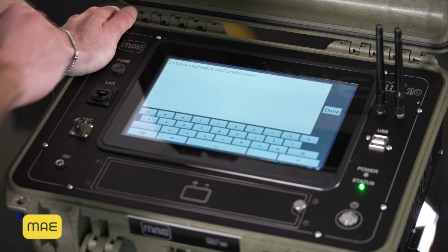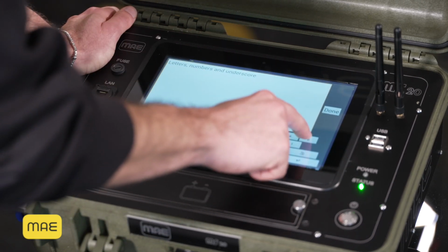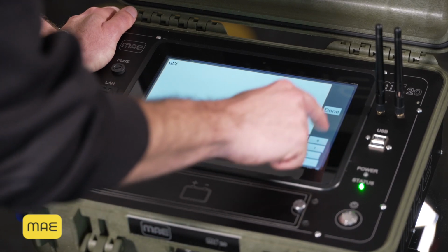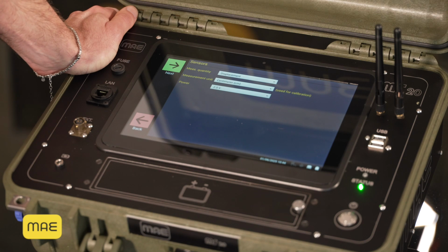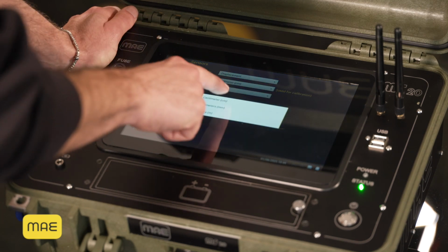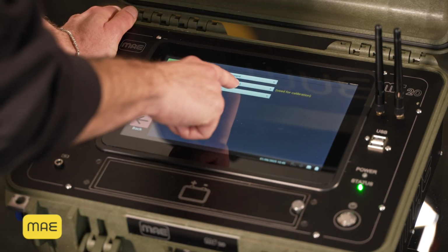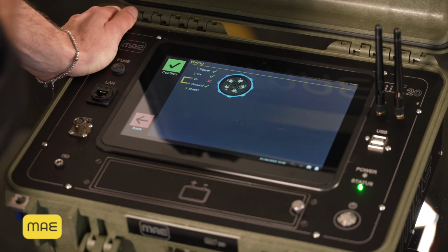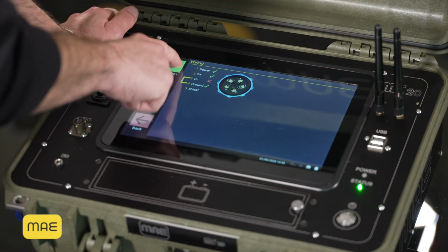We're going to use a name for the transducer and a model, for instance, 5050. Next, we have to select what kind of unit we are measuring. In this case, it's going to be displacement, centimeter, and then the power supply of the sensor. Usually, it's 5 volt. At the end, we have the cable configuration for this sensor, if needed.